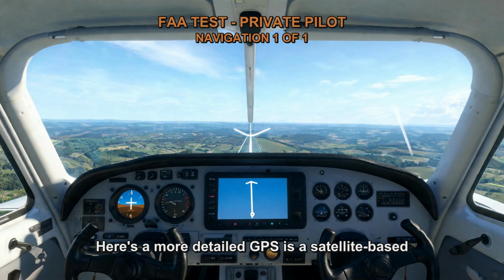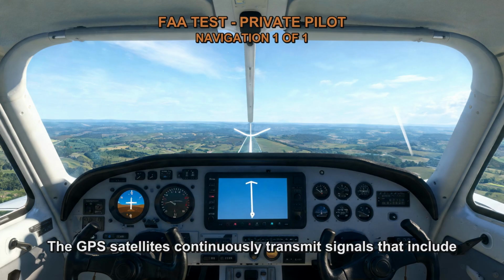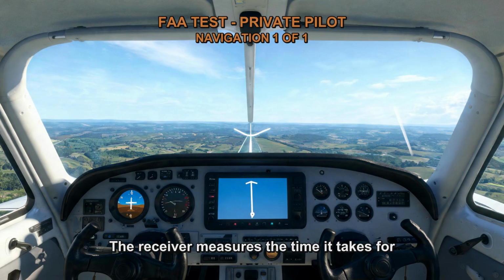Here's a more detailed explanation. GPS is a satellite-based navigation system that consists of a network of orbiting satellites, ground-based control stations, and GPS receivers. The GPS satellites continuously transmit signals that include information about their location and the precise time the signals were transmitted. To determine its position, a GPS receiver needs to receive signals from multiple satellites. The receiver measures the time it takes for the signals to reach it from each satellite and uses that information to calculate the distance between the receiver and each satellite.